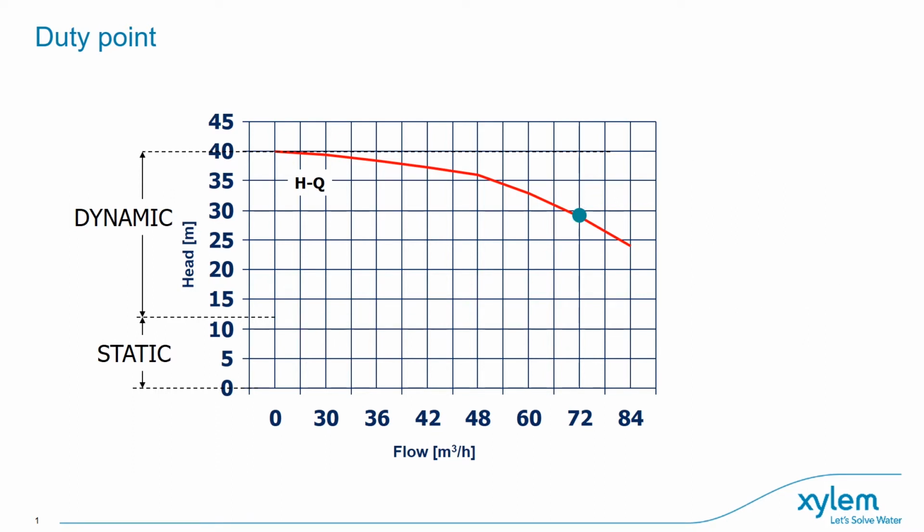So this is where our variable demand comes in, dependent on the different pressures and flows that are required. So we can have a constant flow, but with varying demands in peak and trough times that can increase or reduce the friction loss accordingly, which we have to take into consideration when we are designing the package.